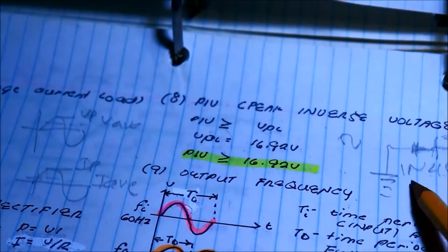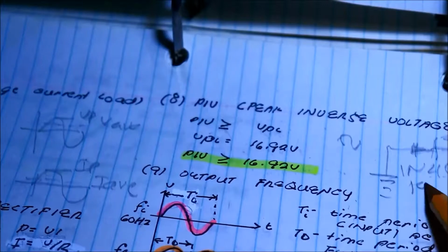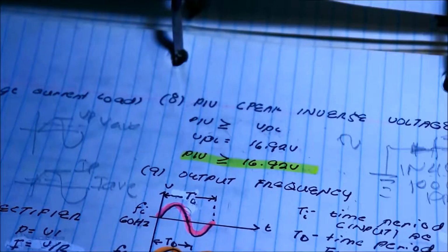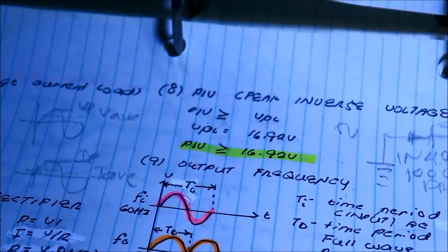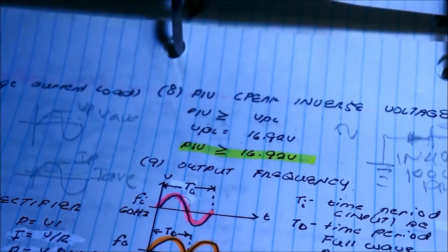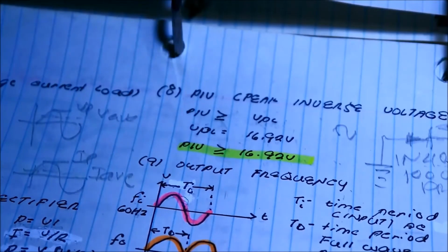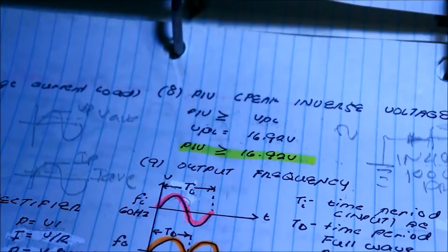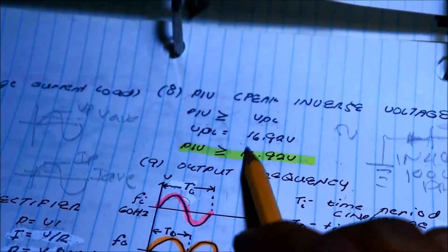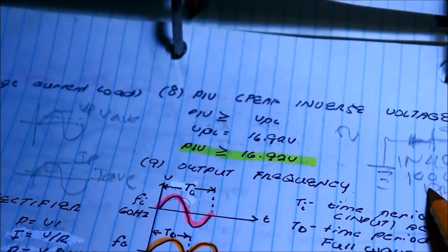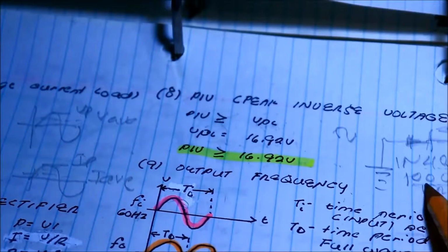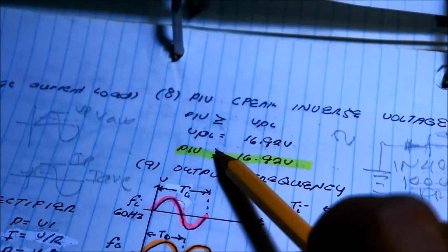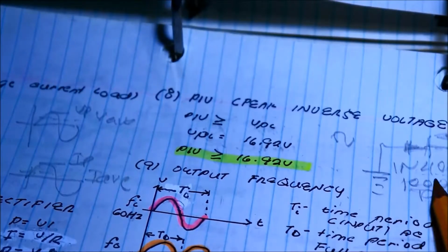1N4007, in the data sheet I read, it's 1000 volts peak reverse voltage, or when you're matching with RMS, it should be 50 volts VRMS, but we are only using 12 volts VRMS, and then 12 volts, or the voltage peak 16.92, but the voltage repetitive or PIV of this 4007 is almost 1000 volts, but the voltage peak of the load is just 16.92 volts, so it's okay.